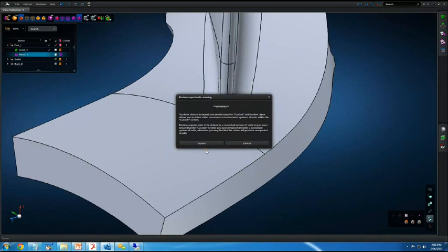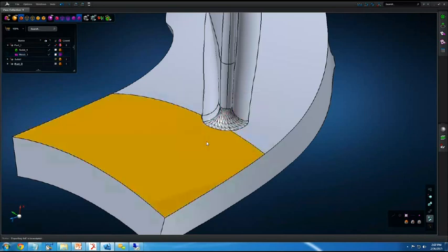And Apex is going to give me a warning that because I have chosen the custom unit system, my units may not necessarily be consistent with one another. However, I have verified my units are all consistent. I don't have inches with kilograms, etc. So it's just giving you a warning saying that this could cause problems if you had inconsistent units when the Nastran solver goes to solve. So I'm going to go ahead and export. Like I said, I've already verified that everything is correct.